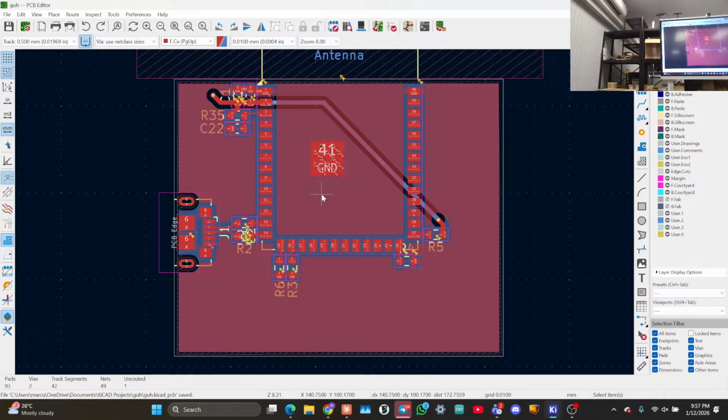For the purposes of this course, we're only going to put all the components on the front side, because that means that if you ask the company to solder for you, it will be cheaper. If you do both sides, it's very expensive because you cannot use economic assembly. You use standard. Economic assembly only allows you to assemble one side.